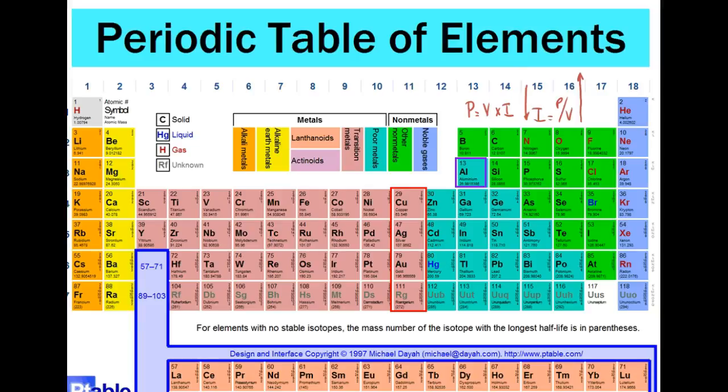So this is what these high tension lines are doing. They step the voltage up extremely high for transmission, and then they step it down for safety. And that's why they use aluminum. So your high tension lines, or higher voltage lines, use aluminum. And some of your lower voltage lines still use aluminum, but when they start getting down around your house, that's going to be copper, right?